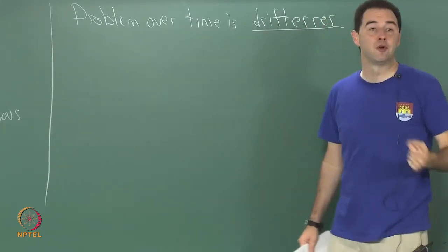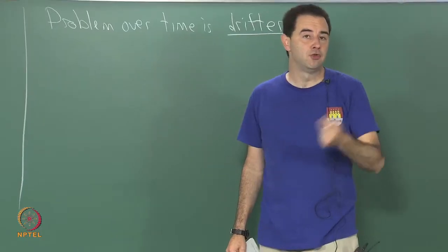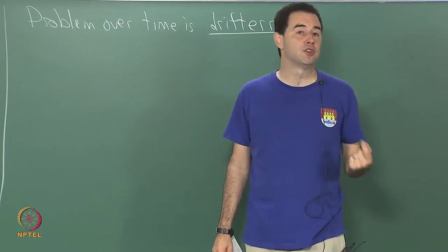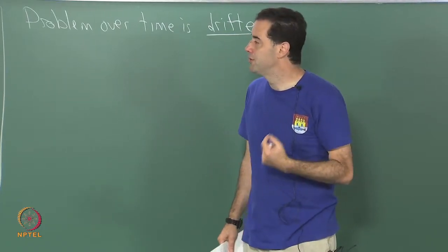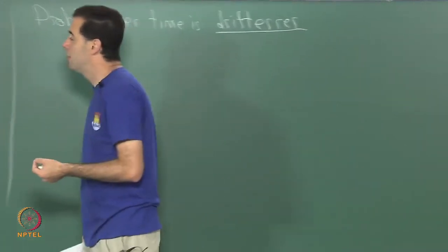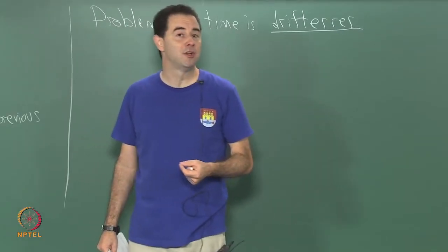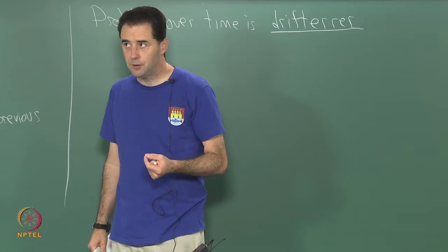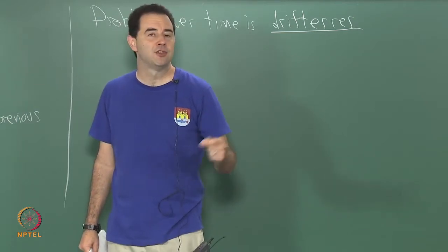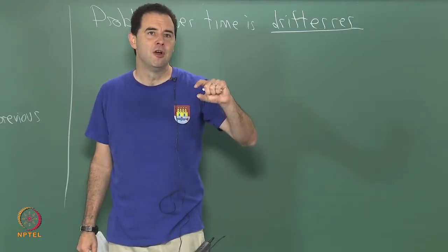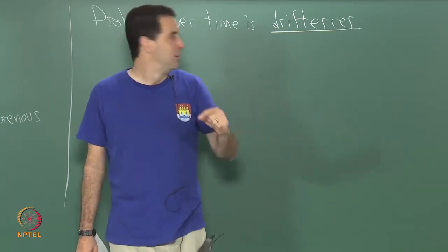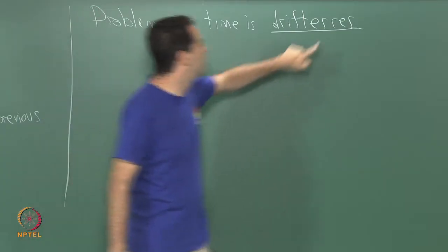It's a gradual divergence between the true orientation and our estimate of the orientation. These will gradually get worse and worse, especially because most of the errors in this process are systematic. They're due to calibration difficulties in some way. It may be that the gyro along the x-axis always gives a reading that's an overestimate by a certain amount, and that will continue to increase the drift error linearly.